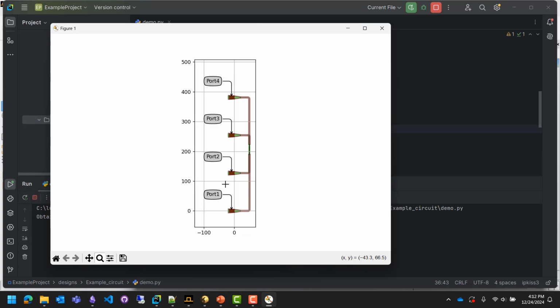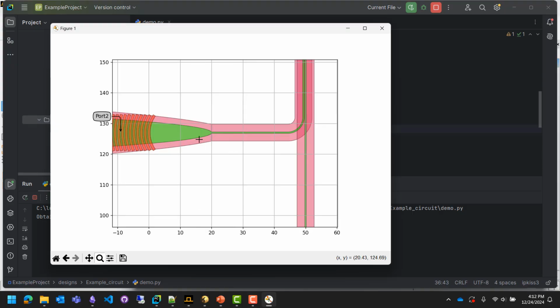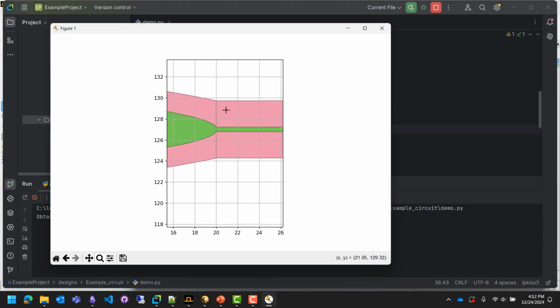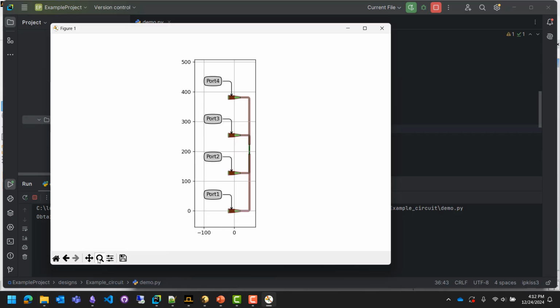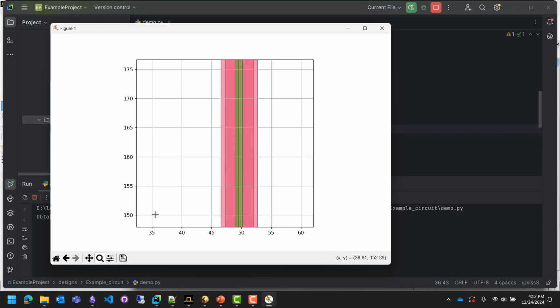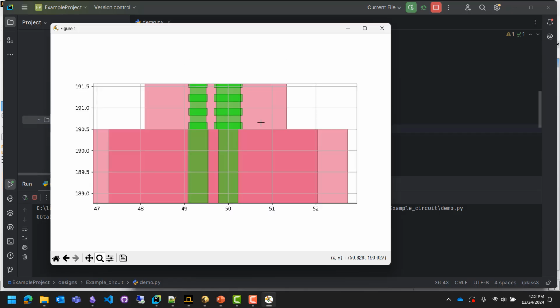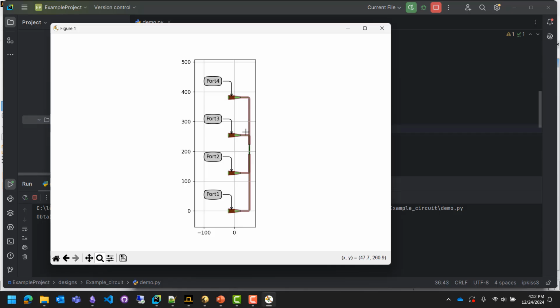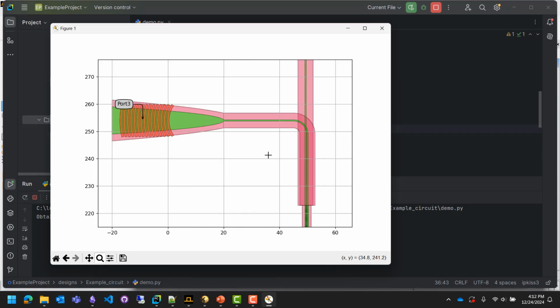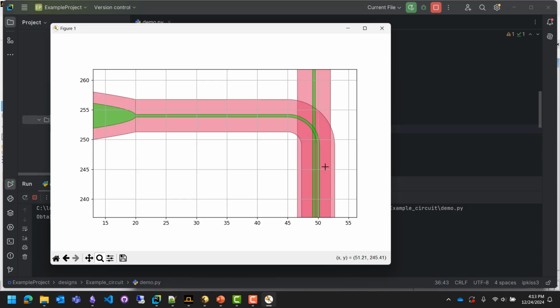So we can take a look down here, and we can see that the grating coupler is connected nicely. And then here's our waveguide. And if we check our contradirectional coupler, it connects nicely to our device. What you do want to be careful of is up here in port 3. If we follow port 3, you'll see that a crossover actually happened. And the reasoning is because of the port naming.